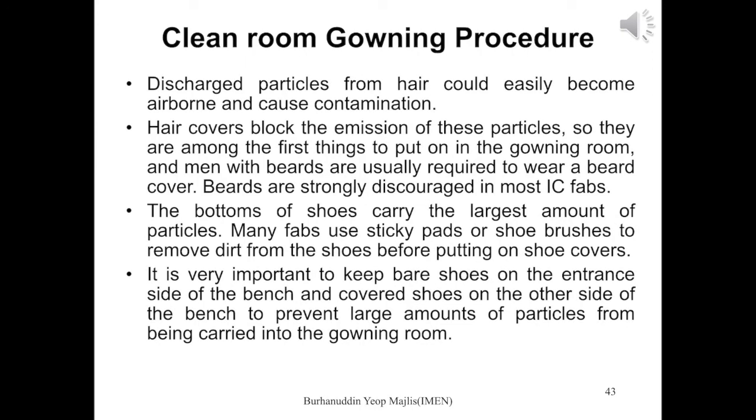Discharged particles from hair could easily become airborne and cause contamination. So hair covers block the emission of these particles, so they are among the first things to put on in the gowning room. And men with beards are usually required to wear a beard cover. Beards are strongly discouraged in most IC fabrication.